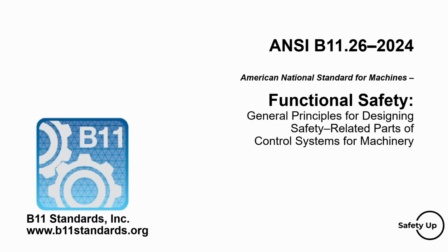The Preparations for Functional Safety Design section outlines the steps for conducting a risk assessment, identifying risk reduction measures, defining safety functions, determining reliability design specifications, and selecting appropriate input, logic, and output elements. It emphasizes the importance of a thorough risk assessment to identify hazards and determine the necessary safety functions to reduce risk to an acceptable level.